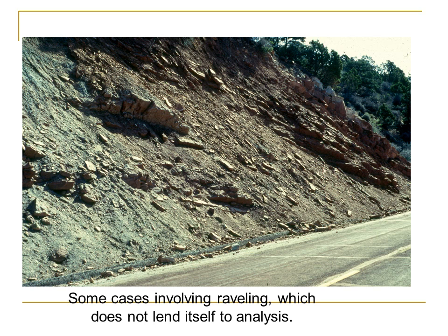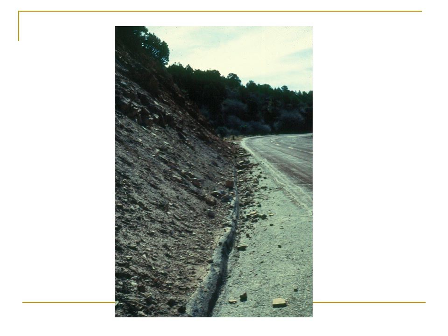This is raveling, and it can occur very commonly in soil slopes, but also in rock slopes. And here are some examples. Here's one view of raveling. Here's another view of raveling on a rock slope, and this was taken at the end of a winter season in Utah, where each year the State Highway Department had to clean up after these rather small raveling failures that occur predictably each winter season. They might seem small, but they can also pose significant danger to people driving along the roadway. So that's another view of a raveling failure.